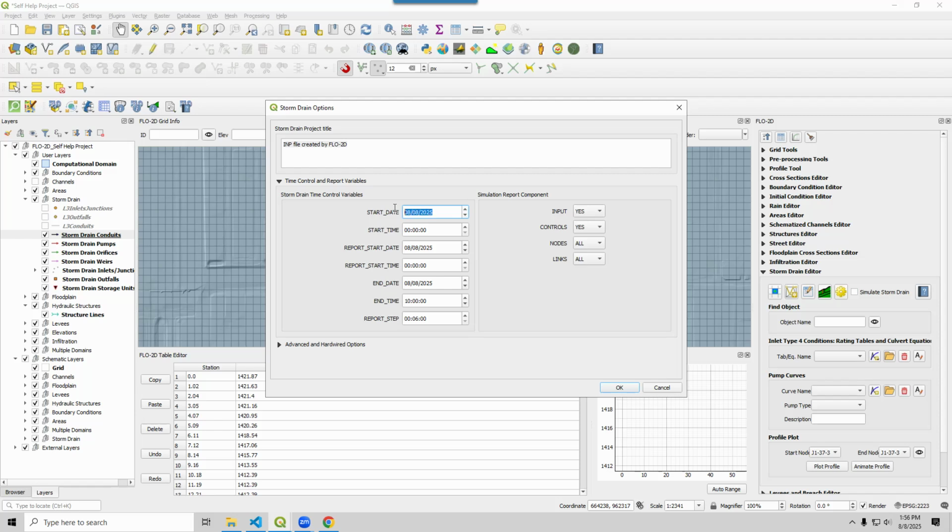The start date for the simplified lesson is not important because we do not have to sync this to any other data. The start time is important. It needs to be the start time of the simulation, and of course, our start time is 0. And the end time is important. It also needs to be the full simulation runtime. It can't extend beyond that, and it can't stop before that. It needs to be the full simulation time.